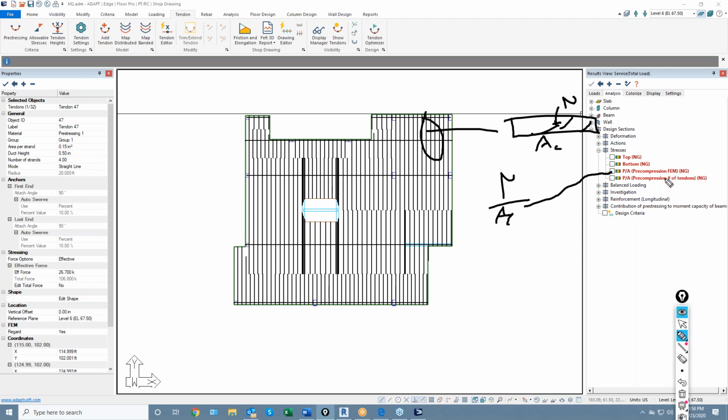That could be a little bit tricky because if the slab and the layout of the walls and the supports was in such a condition where you actually started to develop in-plane restraint, then you would see a huge drop-off in pre-compression. And some users would fight that. They would say, well, we know we're going to detail the slab to release the slab and allow it to shorten, or we might have pour strips or a combination of those two things, but the program doesn't really simulate that. So I'm getting this drop of pre-compression that's kind of diverting into walls and supports.